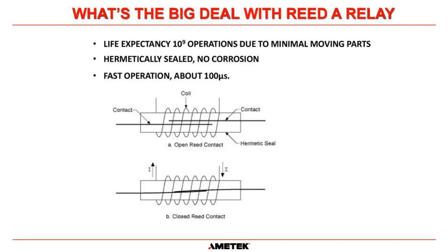So first of all, a reed switch, unlike a typical relay, uses two contacts that are biased either closed or open, whichever you want, with a magnet, and then the coil of wire is connected such that it bucks out the magnetic field of the magnet, and that's what allows the contacts to change state. So reed relays until the last 20 or 30 years were very common in voltage monitoring and detection circuits, sample and hold type circuits, things like that. I believe the phone company used them in their switchboards because, again, reliability.